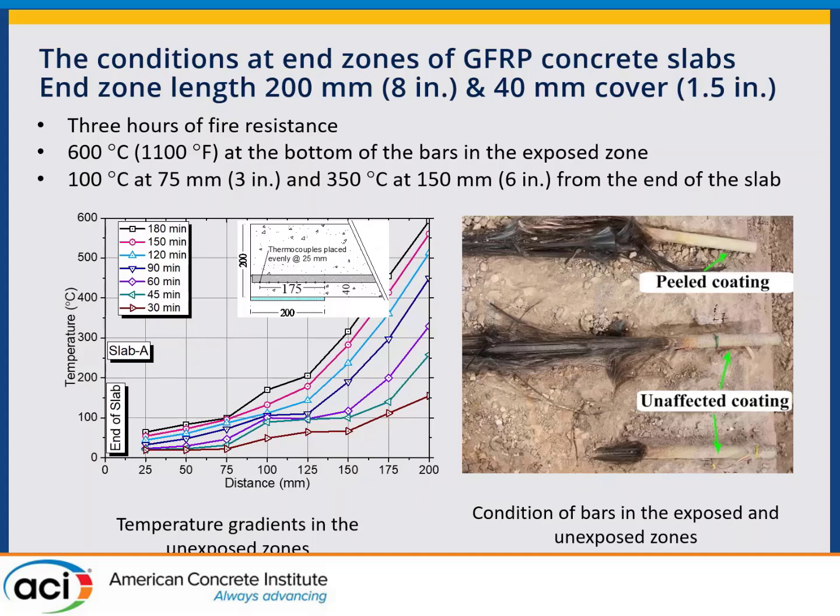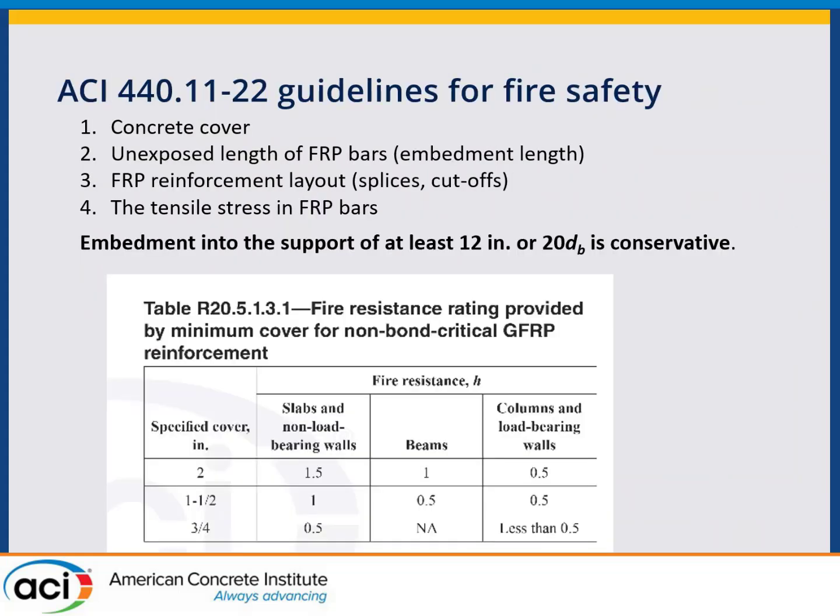So you're only just affecting the polymer at that stage. And you can see here that visually most of the coating is intact. It's starting to peel and things like that. But this, of course, is where it's all burned away in that higher temperature zone. But it just shows that we're getting quite a bit of strength developed even with these very, very short embedment lengths in the relatively cool zones.